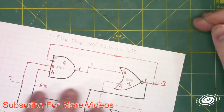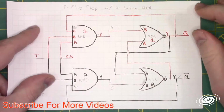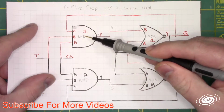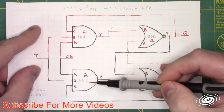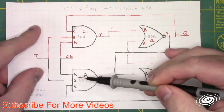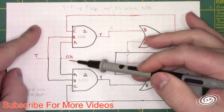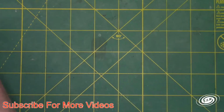And then the other version is with the RS latch system, the NOR gates. You have 2-input NOR gates, and then you set up your SR latch system, and then you take a tap off of the first NOR gate to this 3-input AND gate, and you do the same for the second AND gate with 3 inputs. Then you just have your clock and your toggle, your T, and again I tied T high, and you can see that no matter what clock signal I put in, it glitches and errors out. So let's look at the circuit here.